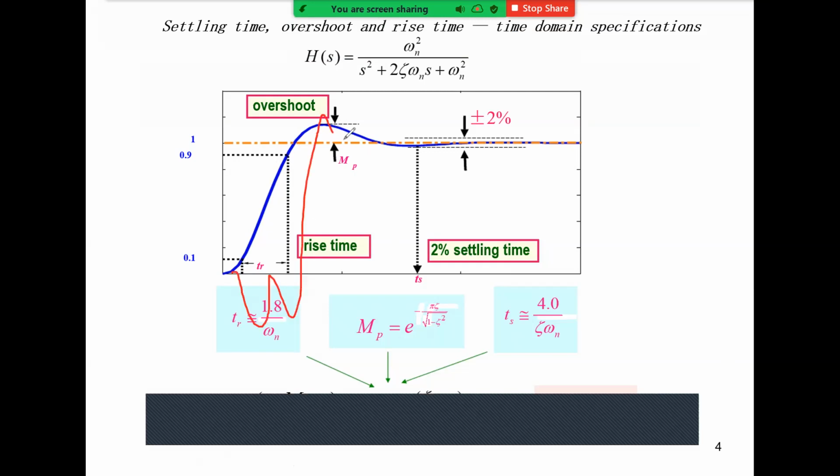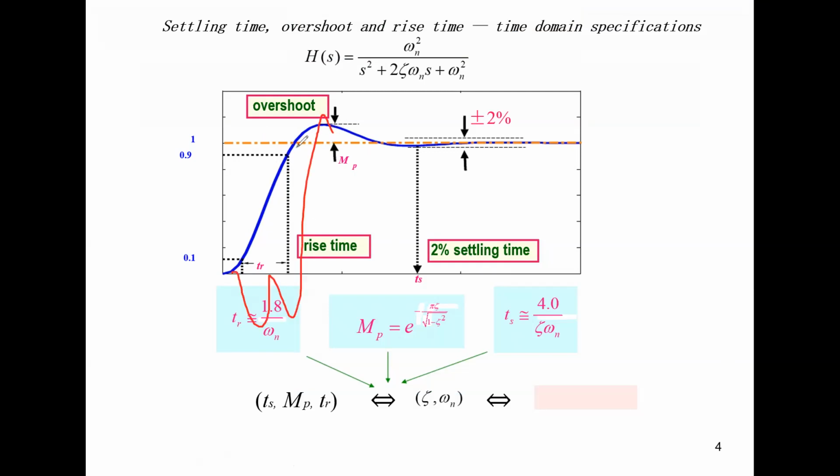If that happens, we just consider the overshoot, the first peak after it goes over the final value. Everything under that, we don't consider as overshoot. So whatever happens, as long as it does not become bigger than the final value, we say the overshoot will be 0.